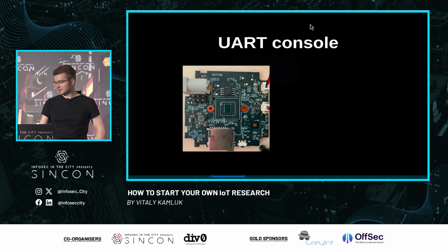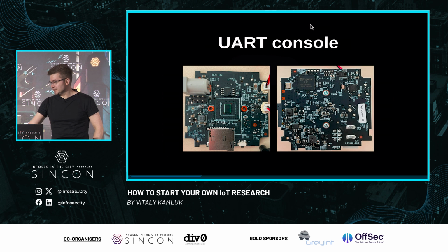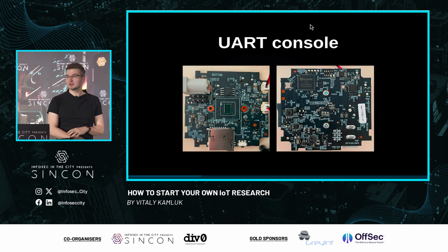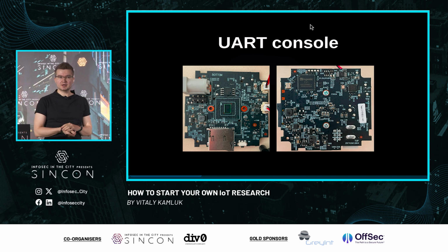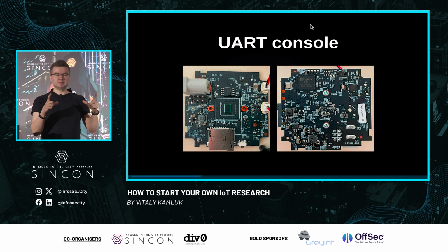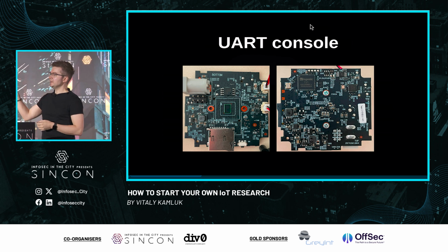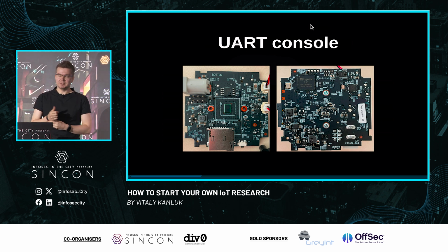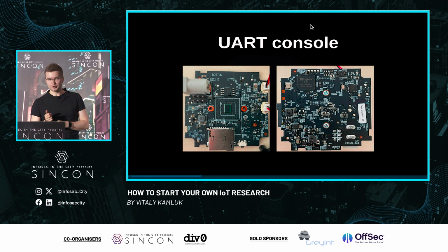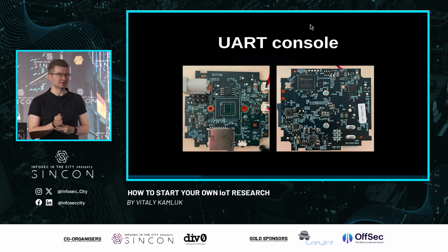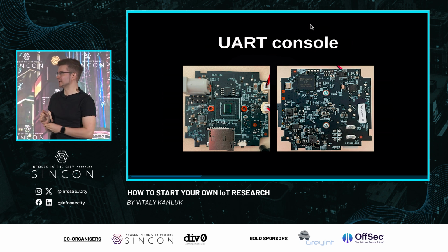But the challenge with this device was that this UART console normally comes with pins that are marked on most consumer devices. If you take network routers, pretty big PCB boards, they normally have not just numbers, but even names written on the boards. In my case, there was nothing like that. So I looked and looked and looked. There were some numbers, like cryptic alphanumeric identifiers, but they didn't really explain what they meant.